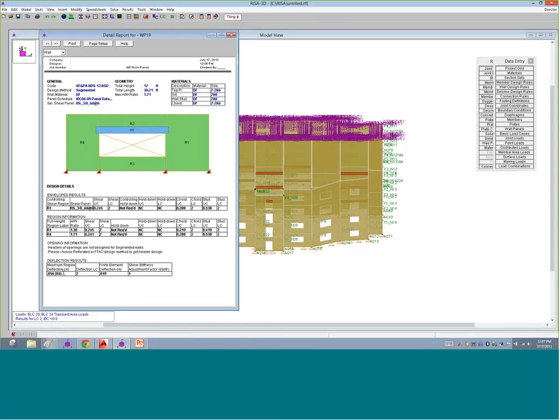Deflection is based on what we see here, the maximum deflection is R4, this one right here, and it gives us what the deflection is. It tells us it's 0.056, and then it also tells us what the finite element analysis gave us. So we have two types of deflections. One's based on the calculation, and one's based on the finite element analysis. And we can see that they are slightly different. You can use this adjustment factor to help get these closer together, so you fine-tune how stiff that wall element is.